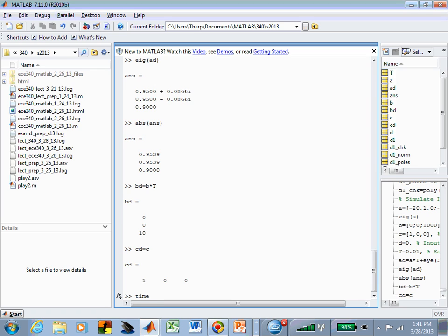That was minus 1/2 before we denormalized it, and then it moved by a factor of 10. It's now minus 5, isn't it? That's going to give us an e to the minus 5t piece for a decay, and that's going to be the slowest decay. So 5 tau equal to 1. Tau is now 0.2. And we want 5 of those time constants, and that's how long our transient's going to be. So our transient is going to last about a second.